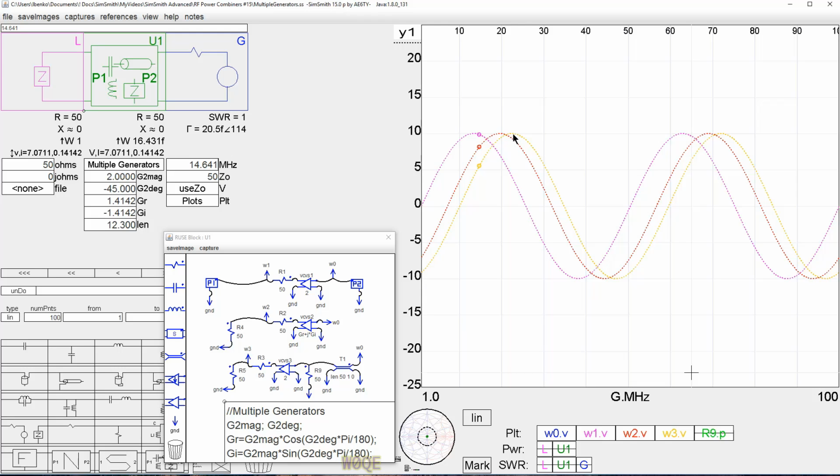So if you had two signals you wanted to control that were offset by a certain number of milliseconds, you can't use this construct anymore. You have to put a delay line in there. Either one of these ways to do this is equally good. They both work the same way.